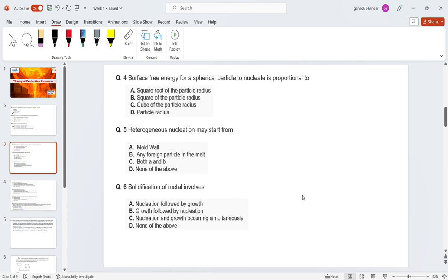So when surface tension increases, that is a major defect in soldering. What are the additives added during soldering? If those additives are not added, the solder won't wet your surface. What I mean by wetting is the forces between your soldering alloy and the outer surface on which you want to do wetting.